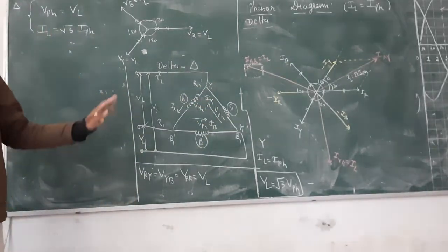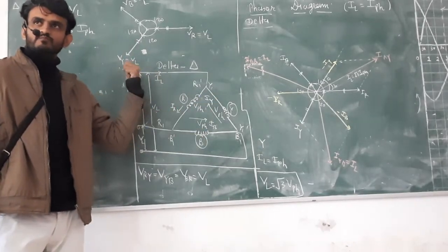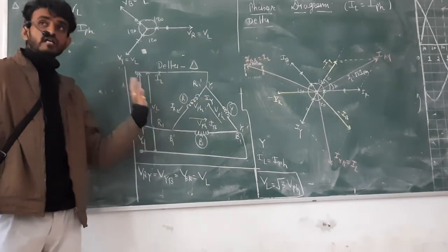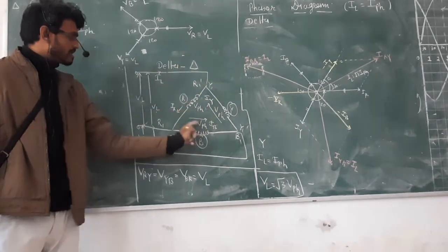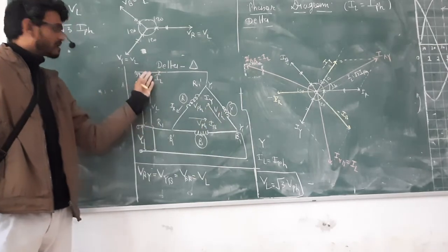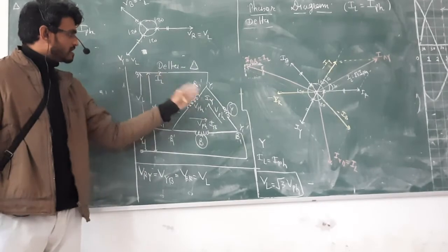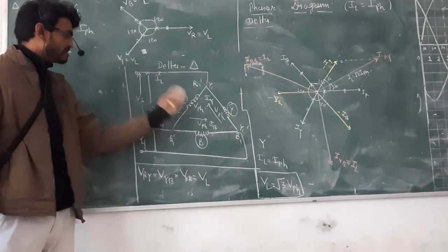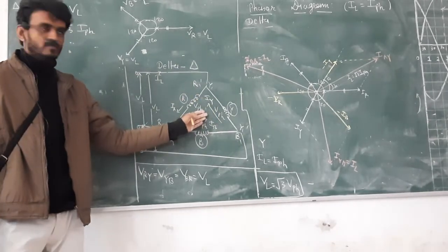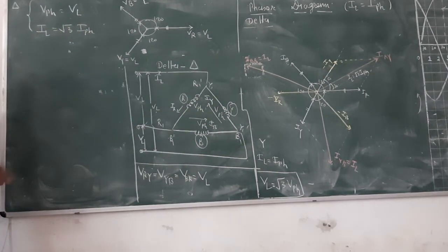In electrical engineering, there is a concept called harmonics. It will set the current out of phase in such a way that there will be circulating current and it will heat the winding. You measure 5 amperes here, but it happens that the addition of these two currents is not 5 but 6 or 7. So extra current will be circulating in this winding. Okay, so write it down here.